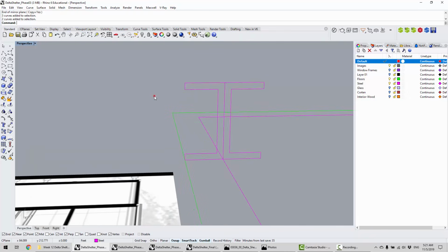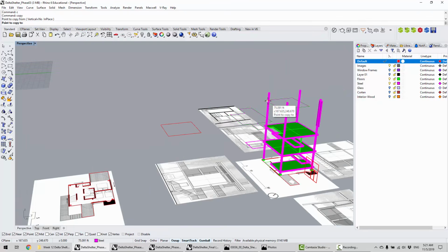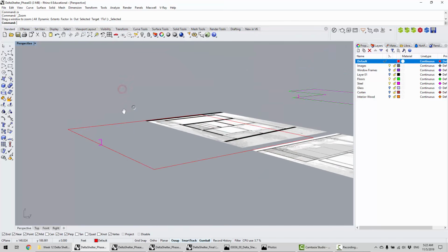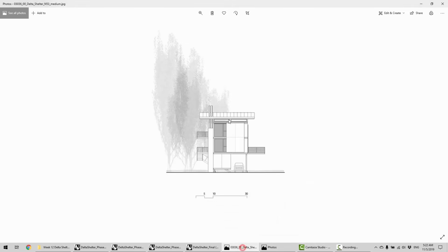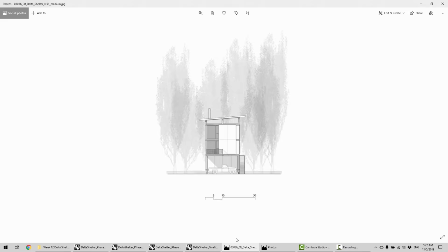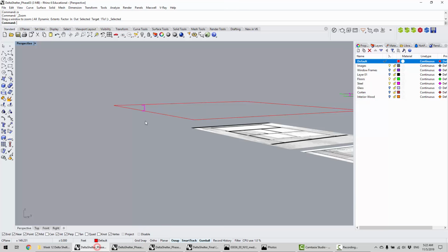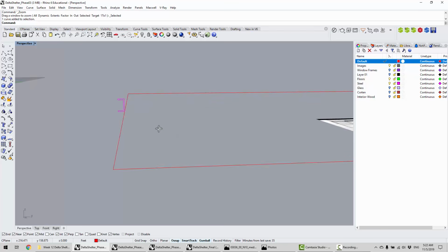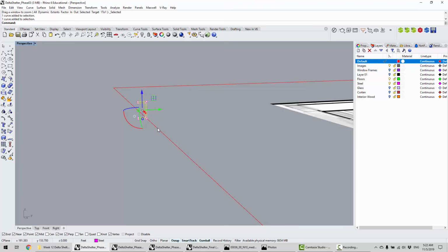We're going to use this to make the I-beam profile that you see on the ends here, on each floor, as well as the flange of these I-beams. And what you do here is arrange it and put it together like this. So this side snaps to one of the edges of this square, for example.